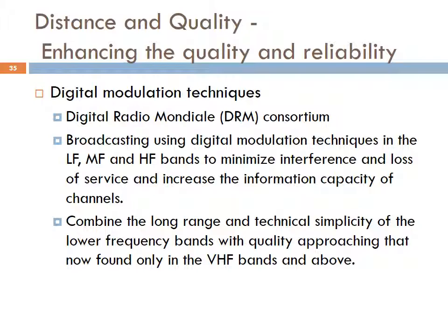However, there are moves to enhance the quality and reliability in this region. In particular, there is an international consortium called Digital Radio Mondiale, which is already broadcasting using digital modulation techniques in the LF, MF, and HF bands to minimize interference and loss of service and increase the information capacity of channels. This system is aiming to combine the long range and technical simplicity of the lower frequency bands with quality approaching that now found only in the VHF bands and above.